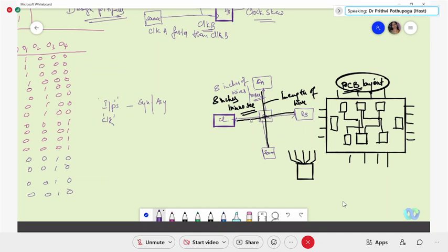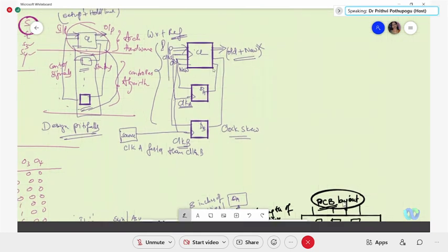And don't go for gating of the clock. Someone said to use a flip-flop in between. When I asked what is the probable remedy, you said between these two, use a flip-flop which will delay the faster one. Say if this is the fast element, use a D flip-flop so that this will be slow and that element of delay will match this point.